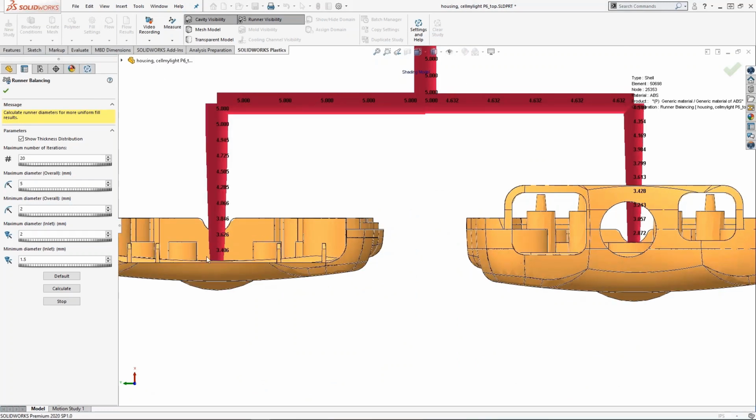With these results, we can think about this a little bit more. Why is this number much larger than this number? Because we want to allow more polymer to flow here, because when the outlet is bigger, there's more flow rate. So there is an increase of flow rate, so it speeds up the velocity of the polymer in this cavity, which is actually faster than this. So it fills up faster.